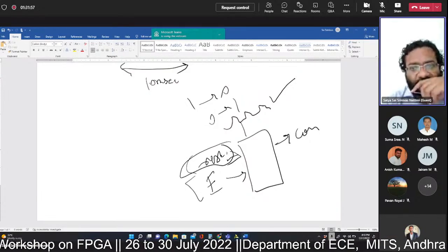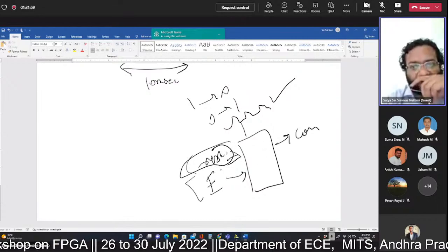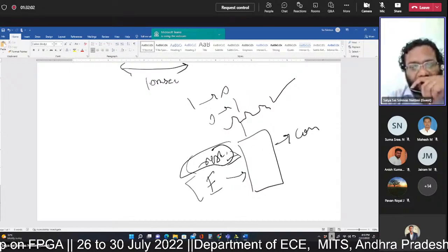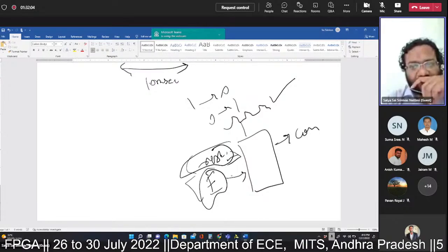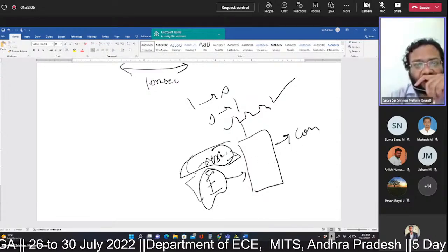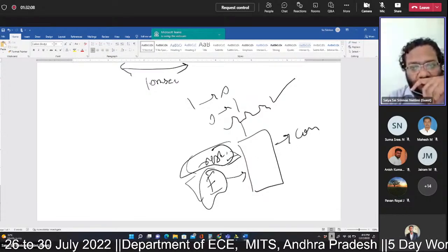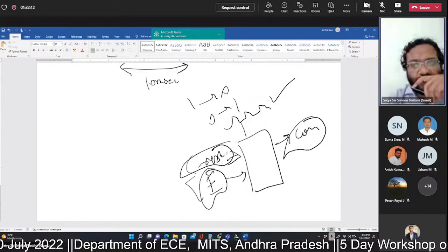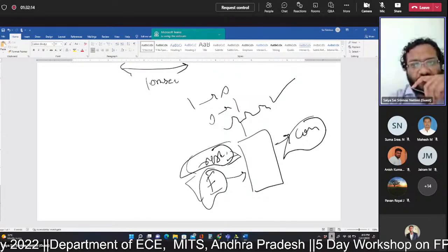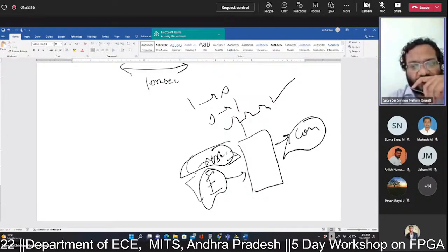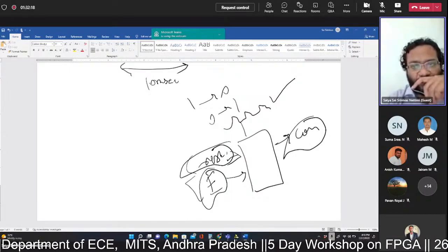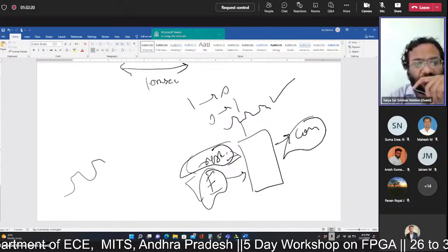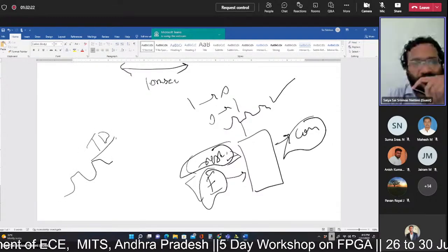So when reset is coming, how the circuit is behaving, when reset is removed, and when enable is given, how the circuit is counting, and when enable is stopped in between, how it is retaining the count value, and again when the enable is resumed, how it is counting. So all these conditions we need to observe in the form of a timing diagram, right?